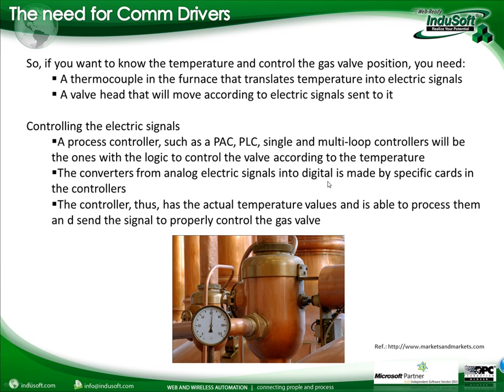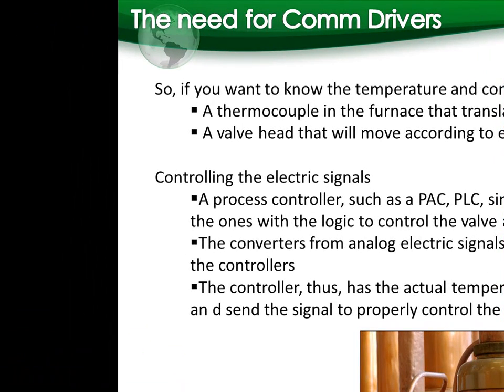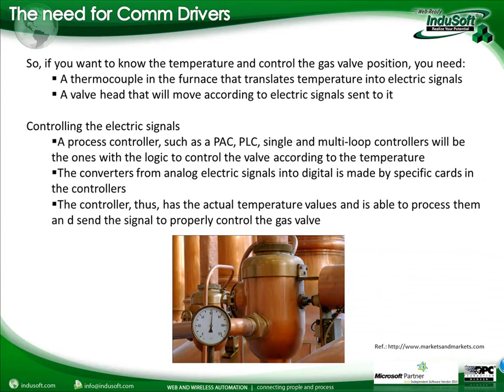So the controller can then process that information, generate a value to open the valve, and then translate that value from the digital information that we have into an actual electronic signal that will be sent to the valve, and the valve is going to have its servo that's going to move to open and close the valve according to the information that we sent to it. So then, knowing the actual temperature, you can also control how much more gas you have to put in there.